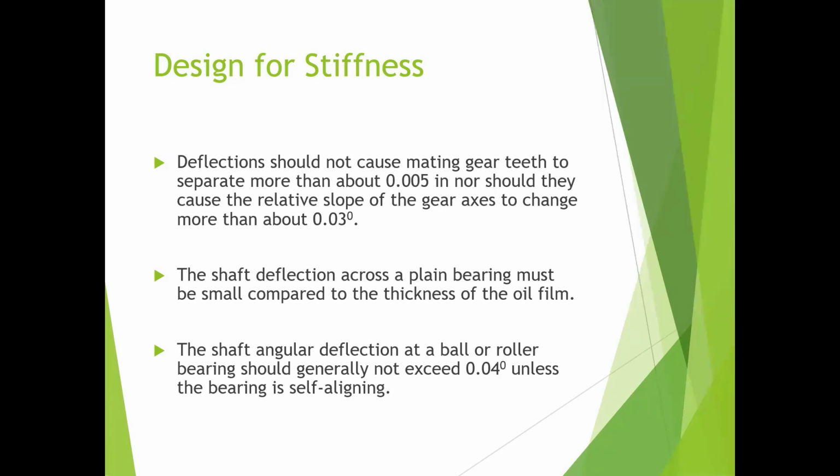If the shaft deflects too much, then, since we apply lubrication at the interface between the bearing and the shaft to minimize friction, a huge deflection will penetrate the lubrication film thickness and the lubrication will lose its function. You understand, guys?